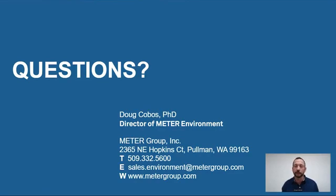If this is a project where you need to understand the water availability to plants, then you probably need to make sure you get those water potential and water content sensors in the root zone. So you really would want to put those in the depth of maximum rooting if this is a plant study. Also, though, even if you're just after hydraulic properties and water transport in the soil, it's the plant rooting and the transpiration through the plants that typically pull most of the water from the deeper soil layers. And so you probably would still want to make sure you have your sensors in the depth of max rooting.